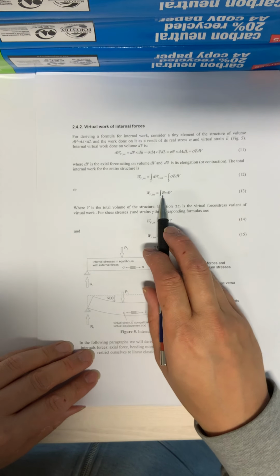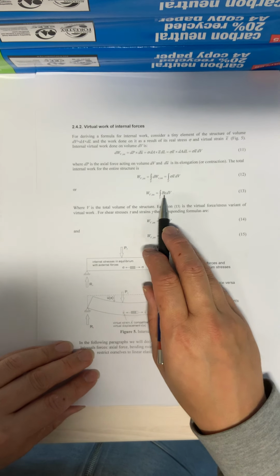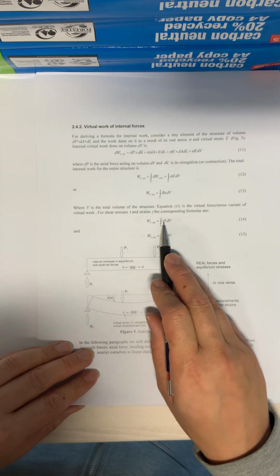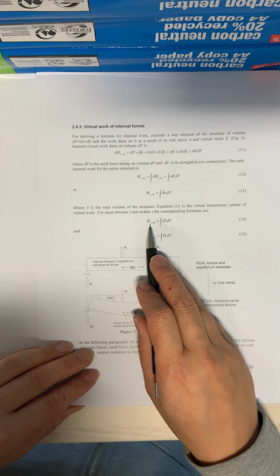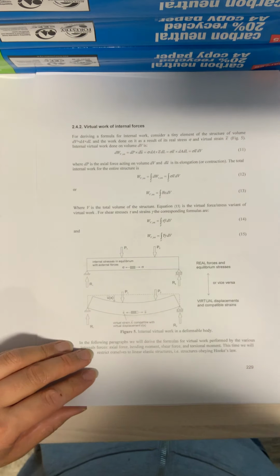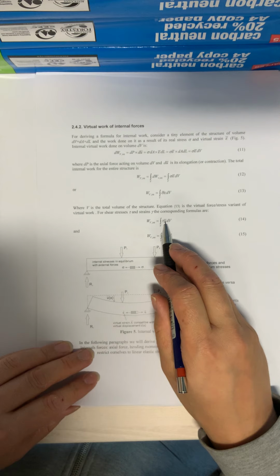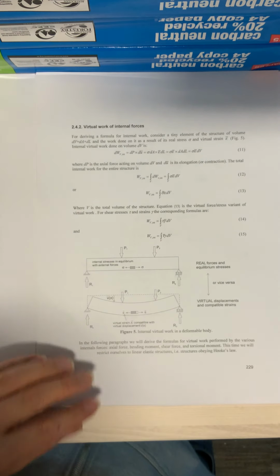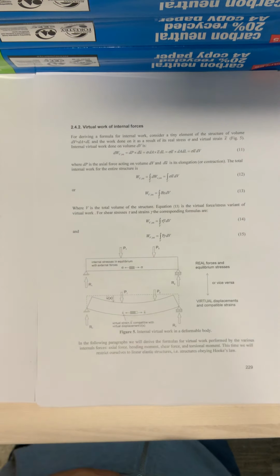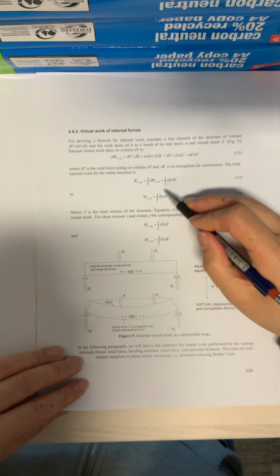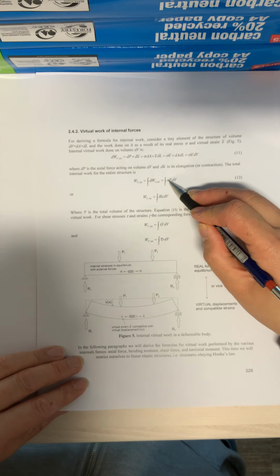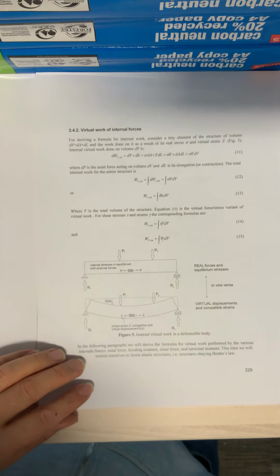So that deals with direct stresses, and we've got exactly the same arrangement when it comes to shear. So you can see the virtual work internal, due to the real shear stress multiplied by a virtual strain over dV, would give you that equation there, or expressed in this way here. So what you can see here is that we can interchange quite easily whether it's the real stress or the virtual stress.